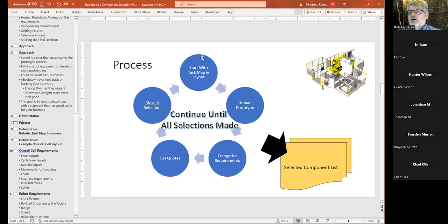So you put yourself in the position of deciding how you want to handle those conditions, sitting in the place of the PLC. And you put yourself in the place of the vision system, and you put yourself in the place of the robot. The robot's the one that's the easiest to imagine because you move your arm around like a robot. As you put yourself in the place of each one of these components, you start to categorize your requirements. You say, all right, if I'm sitting in this PLC spot and I get a sensor reading saying there is a conveyor that's moved over and the box is now in front of that sensor, I need to set that as a condition and then tell the robot, next time it gets around to that step, that there's a box ready for it. So you're like, okay, I could do that.